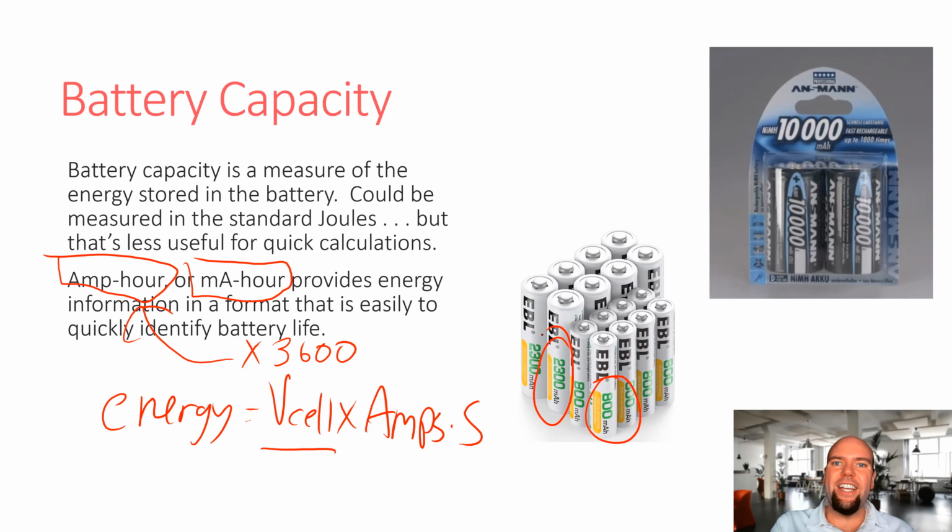And then there is still that issue of the cell voltage, which does matter in terms of overall energy. But usually if you're using a certain battery for a certain application, the system voltage is not as much of an issue as the current. Typically everything's operating with some fixed voltage. The voltage could be converted using a buck or boost, in which case you would have to do a little current and supply voltage swapping. But if it's a linear regulator, then it's easy. Current in equals current out. So it's much more straightforward.